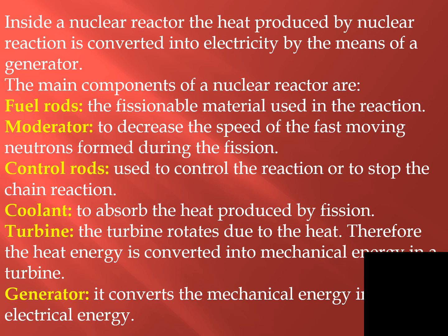The next one is a control rod. What are control rods? The control rods are placed side by side with the fuel rods and suspended from a platform. So you can insert the control rods whenever you want, and you can raise up the control rods at the same time whenever you want. You can lower it into the reactor and you can raise it away from the reactor, that is, from the core of the reactor where the fission reaction takes place.